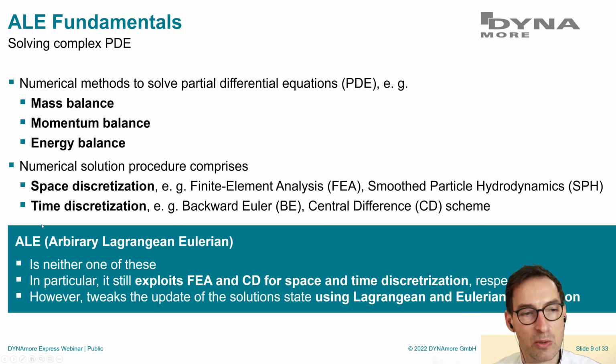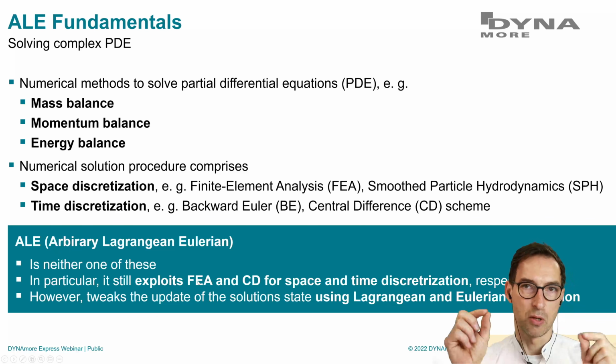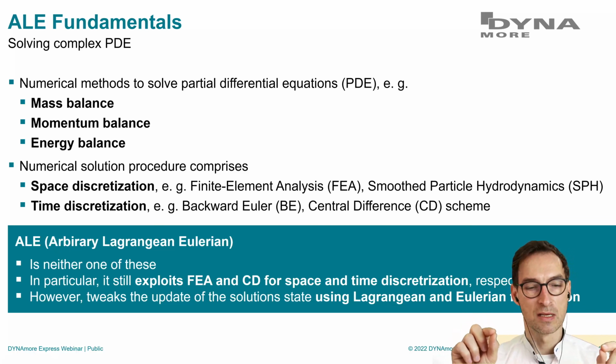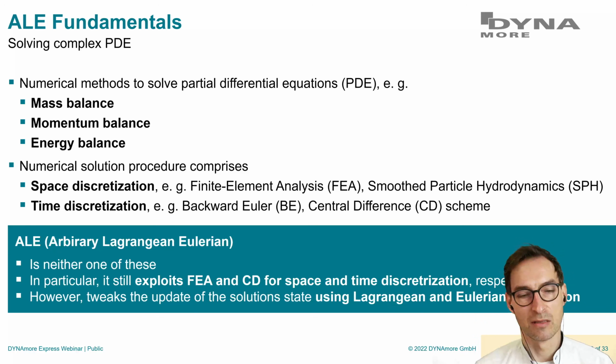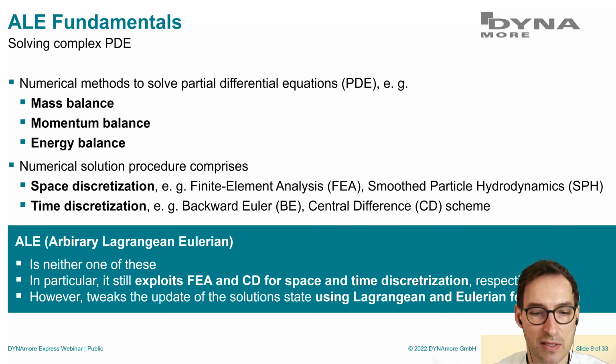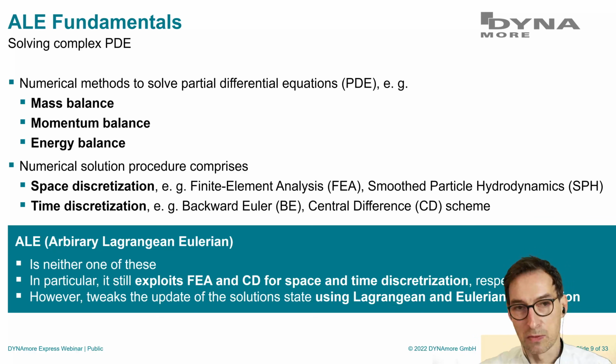Usually we can classify a method as either a space discretization or a time discretization method. The ALE method is neither one of these. It actually uses finite element analysis. That means I introduce a mesh, I have nodes, I have shape functions between the nodes, and then I'm using a time integration scheme, for instance the central difference scheme, in order to obtain a system of equations which I can solve with the computer.